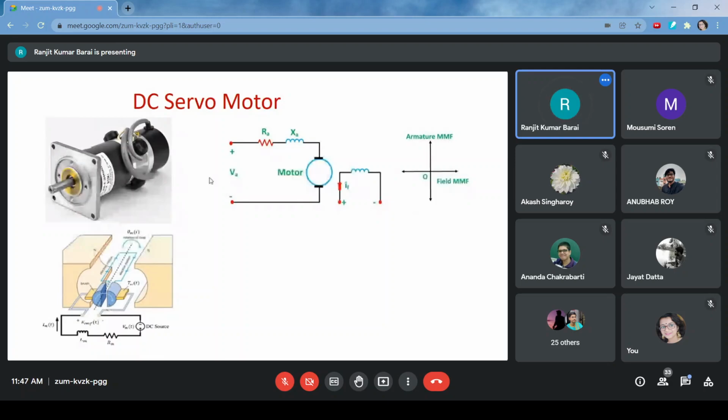Then what we want, an actuator, the desired characteristic of an actuator is that it will be fast. Its response will be fast. That means it should exhibit dynamic characteristics so that its steady state is attained in minimum time. So in order to achieve that, what you need, you have to achieve very small time constant of the system.